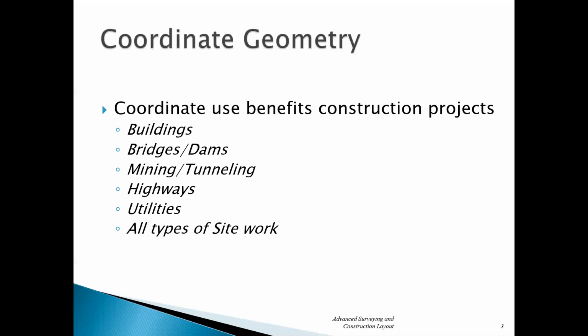Highways, everything on a highway now is done through coordinates of some type. A lot of them now use very high level what they call machine control. All of your coordinate files are downloaded to a controller that's in the cab of either your dozer or your grader or whatever, and that also has servo motors attached to the blades. Your operator just watches the screen, and the machine pretty much drives itself based on your coordinates and raises and lowers the blade as it needs to.